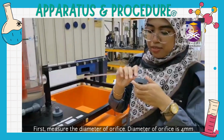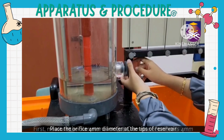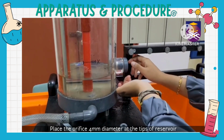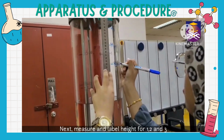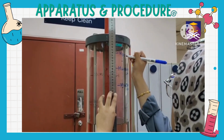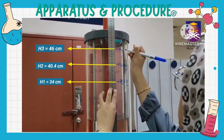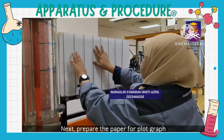First, measure the diameter of the orifice. The diameter of the orifice is 4 mm. Place the 4 mm diameter orifice at the tip of the receiver. Next, measure and level the heights for H1, H2 and H3. Record the data. Next, prepare the paper for plotting the graph.